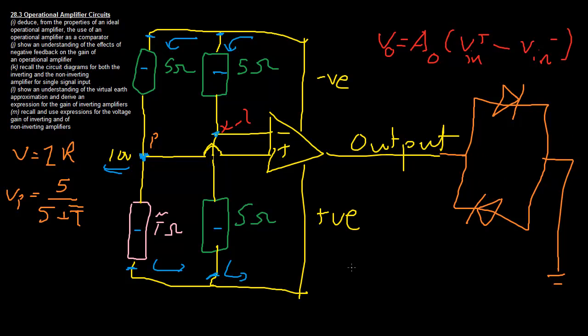So let's take a look at this, right? Let's say on a cold day, the thermistor has a high resistance. You can think of a thermistor like a pool, and the atoms that make up that thermistor are like people in that pool. On a cold day, they don't have much energy, so they all just stand around, vibrating in their spots. When an electron wants to move through that pool, it's hard because everyone is serving as roadblocks, and that therefore has high resistance. Whereas on a hot day, everyone has energy and can move around freely, and electrons can also move freely through it.